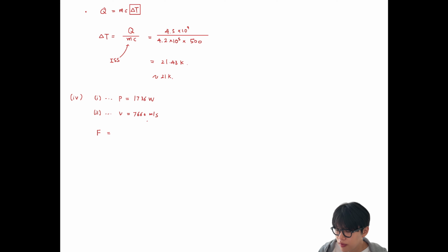So for the drag force, if you use that data, it's pretty easy, right? Because we have the power P equals force times velocity. And if you think about it, it makes sense because the power P is the one you calculated in the earlier question, that's the energy dissipated. Okay, so that's energy lost, and this force is actually the drag force they want to calculate. So that makes sense. So we just substitute the numbers here. F equals P over V. So that's this, and the number is about 0.266 Newton. Oh, that's actually 0.2266 Newton.